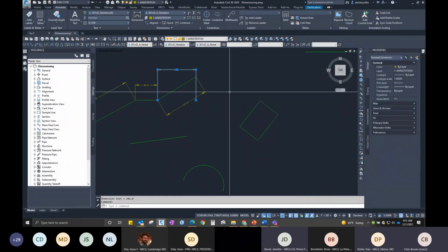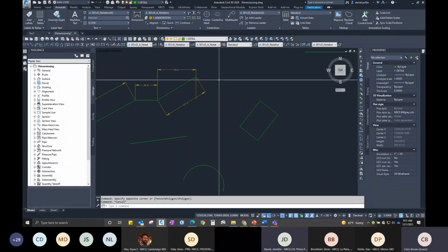Dimensioning again. So Dan, this is Jen again. Just to clarify, the way you phrase that for everyone, the summation of what you're trying to say is that it's not wise to use angular dimensions in profiles because of the vertical distortion, the distance isn't going to be right. That is correct.